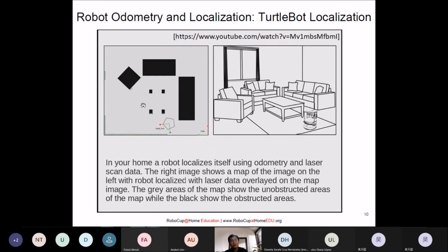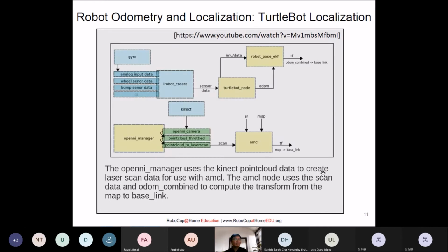Okay, we will explain more about this later on in the actual practical of map building. But over here, please keep in mind that when we use the laser scan to get this map, this is the thing that is going to happen. Because you need to know the height of the sensor, it is not going to give you a 3D scan from bottom to top, but just gives you one slice based on one particular plane. So this is how we get the map.